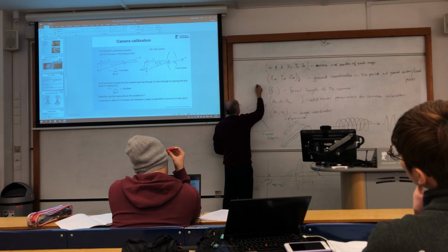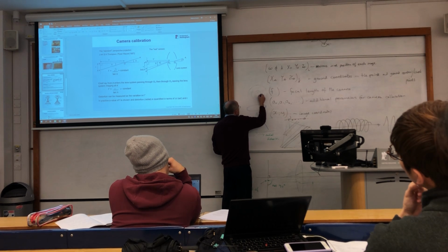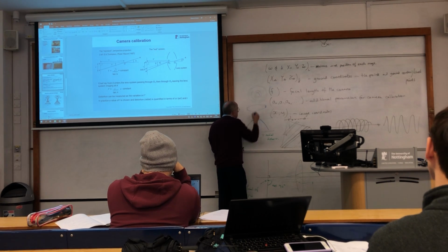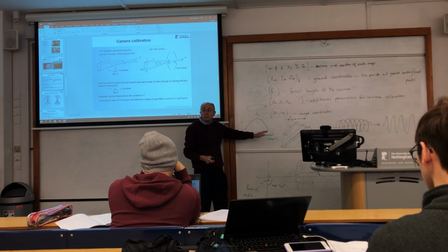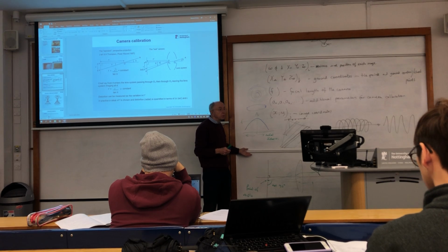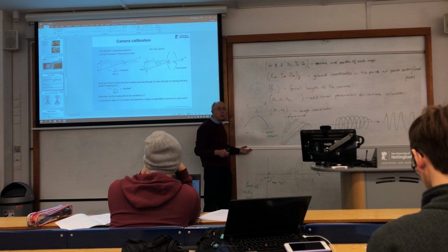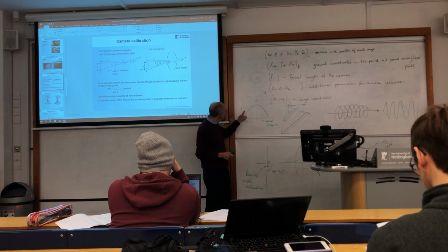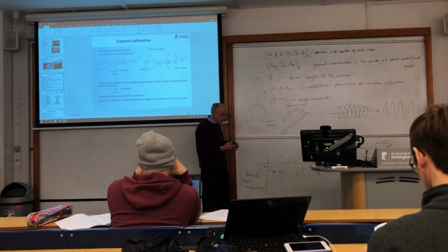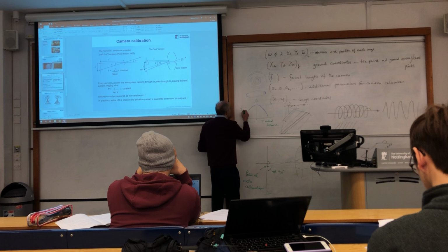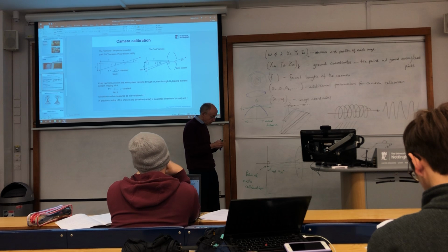So it's circular here. When they make the lens, they grind and they polish in circles around the lens like that, and it tends to cause a distortion like that. Your camera in your smartphone will look like that. The photogrammetric camera that you buy as a photogrammetric camera will be close to that. Close. It will probably be something a little bit more like, perhaps, like that. Very shallow, but nearly flat.